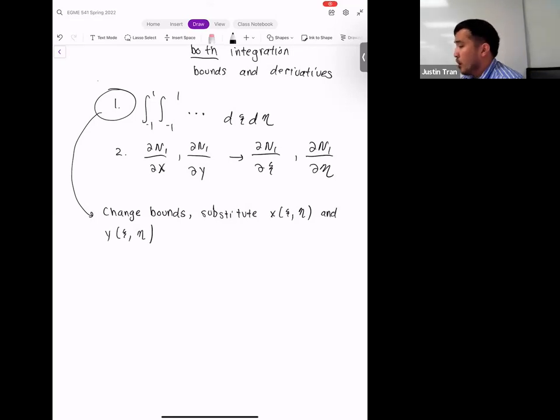And so if you recall, one step that we did before when we first formed our shape functions was that we formed our physical coordinate function as well. And so that's x of epsilon and eta, and then y of epsilon and eta. And so we have to plug those in. Okay. And the last thing that we did was we multiplied by our scaling factor. Okay. So remember, our scaling factor is given by our Jacobian, right? So our Jacobian represents the transformation between those two, and our scaling factor is given by the determinant of that Jacobian matrix. Okay.